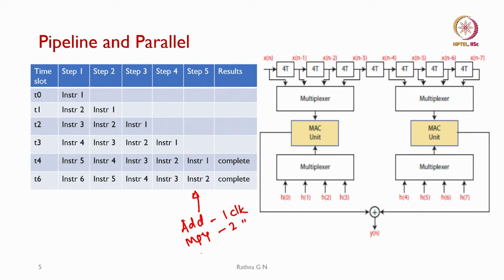We have a load and store architecture, as we said, which is going to take 4 clock cycles, and branches in all these DSP processors, 6, 7, that I have considered, that is the DSK 6713 and the 6748 LCDK board from TI, take 5 clock cycles. So, these are the execution times that we need.